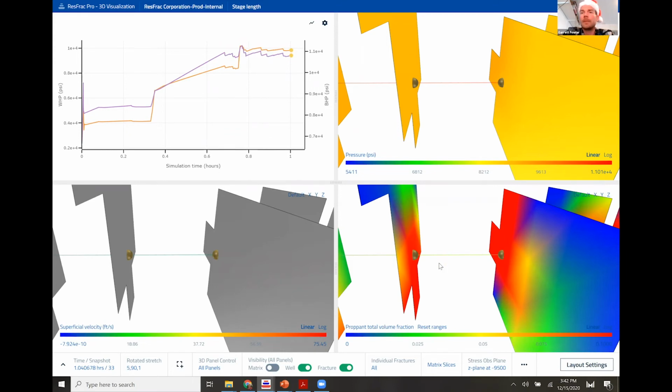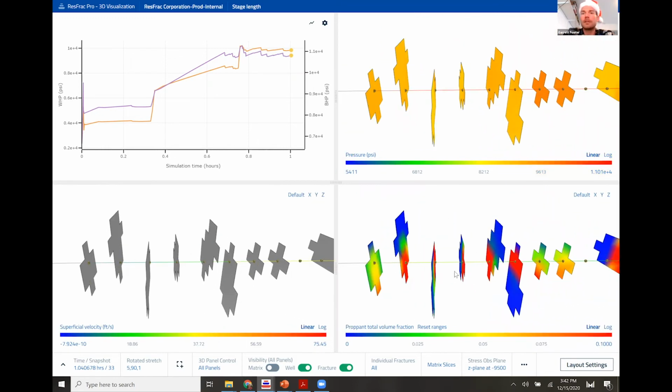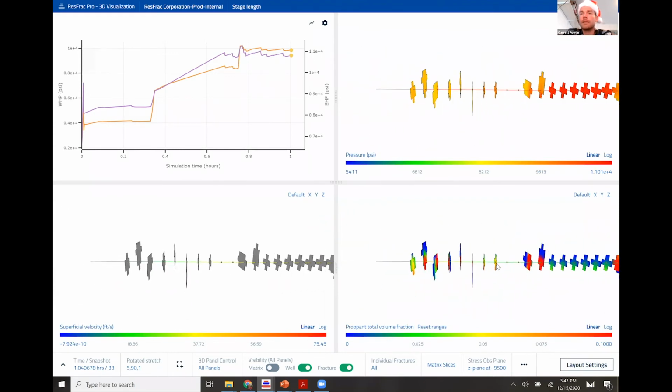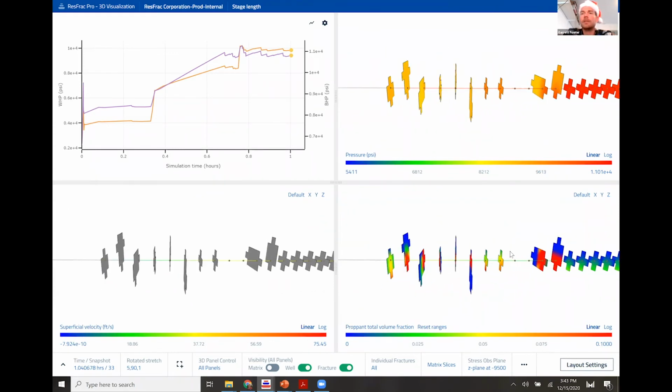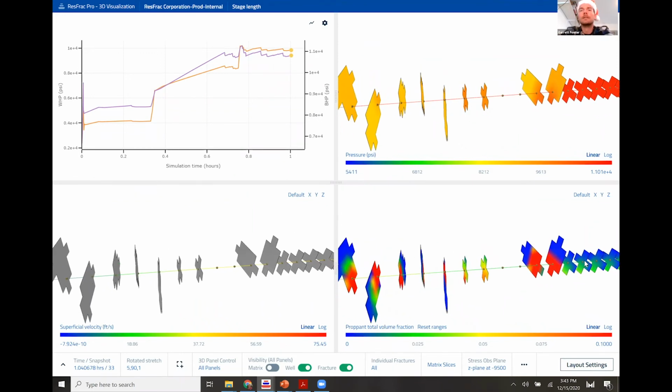And what's going to happen is that once this proppant is deposited in a bed along the base of the wellbore, it's not going to remobilize. It's not going to suddenly then go into a fracture. And so toward the end of the stage, we may actually screen out in the toe because of this proppant accumulation. So I'll mess around with it tonight, and I'll try to send out an update when Tristan sends out the video recording next week.